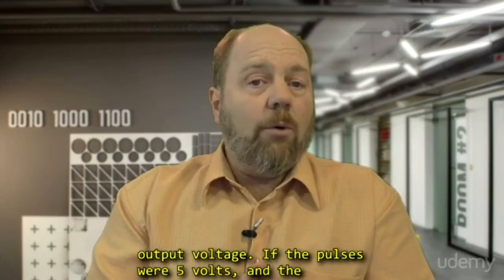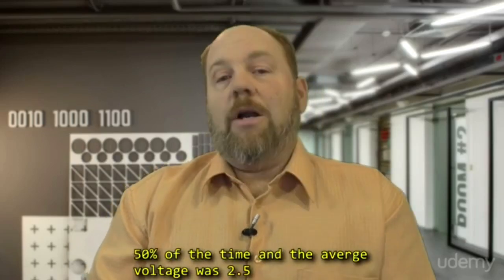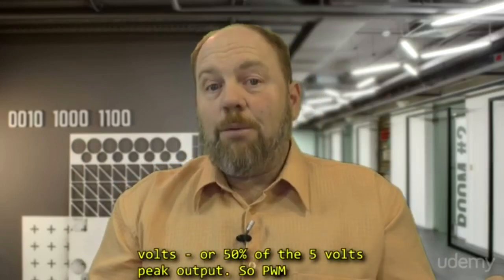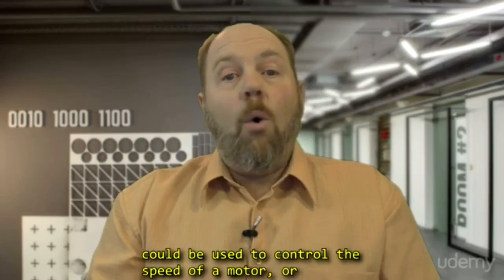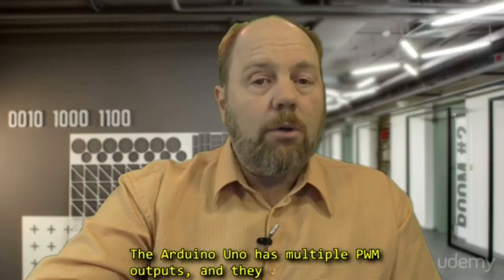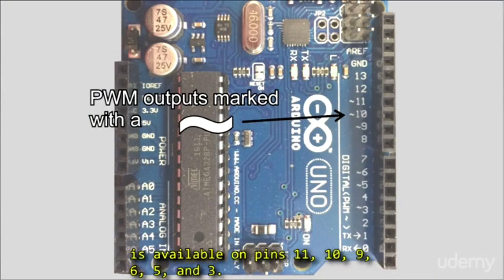If the pulses were 5 volts and the duty cycle was 50%, then the pulse was only high 50% of the time, and so the average voltage was 2.5 volts, or 50% of the 5 volts peak output. So PWM could be used to control the speed of a motor, or the brightness of a light. The Arduino Uno has multiple PWM outputs, and they are marked with the tilde, that is the squiggly dash. PWM is available on pins 11, 10, 9, 6, 5, and 3.